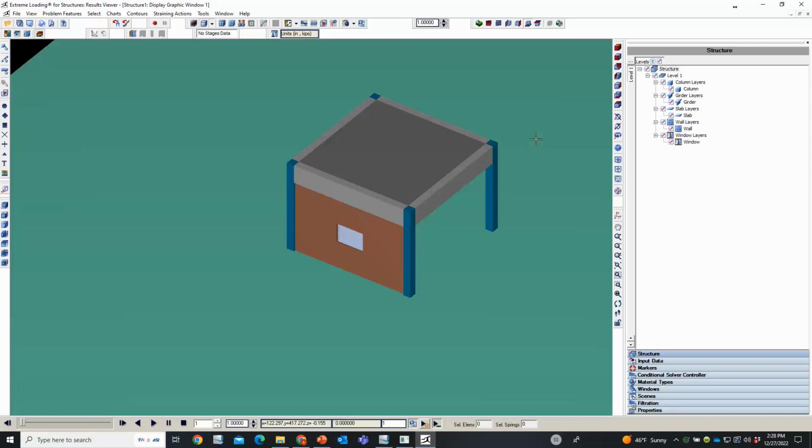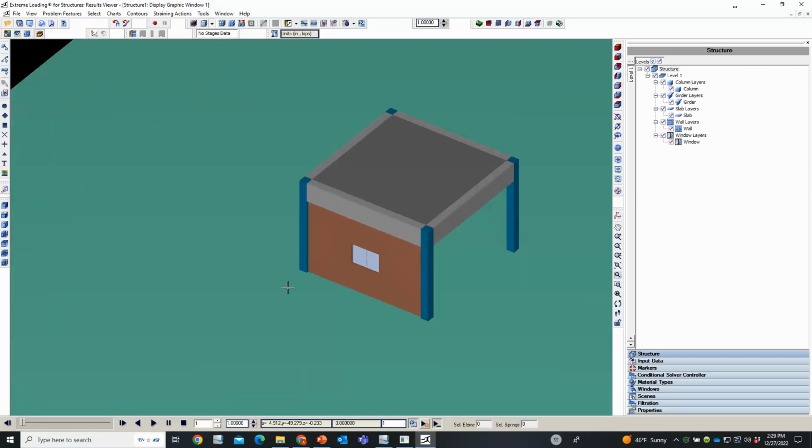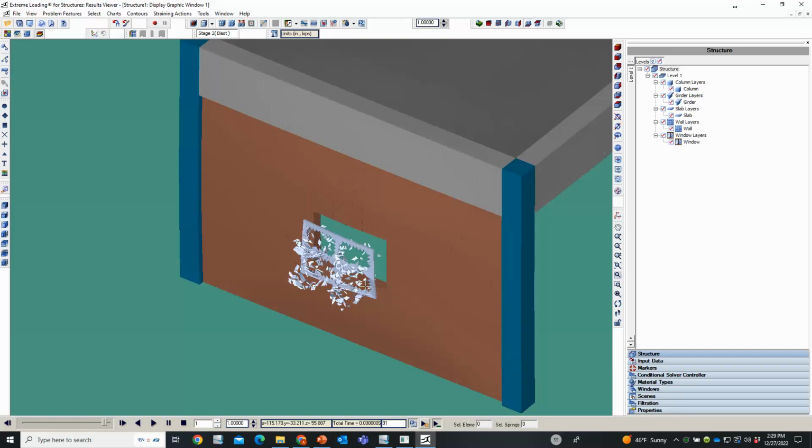This is the viewer where we are having the ground, as you can see in here. If I need to play the results or see the finished steps so far, just click on play. We see here that the bomb pressure arrived at the area of the window, and the window is the weakest location of your structure, so that's why we are seeing damage and deformations. And when you reach here to the roof frame, if you click on update, you'll see that more information is sent to the viewer to be able to see what's happening.